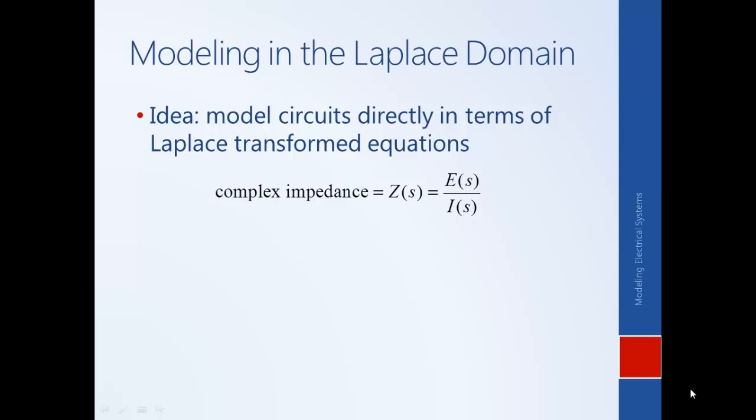Impedance is a similar concept to resistance, and for resistors, impedance and resistance are the same. For capacitors and inductors, however, impedance changes with frequency, and so that's why a more complicated concept is needed. We can't really speak about the simple resistance of an inductor or a capacitor.